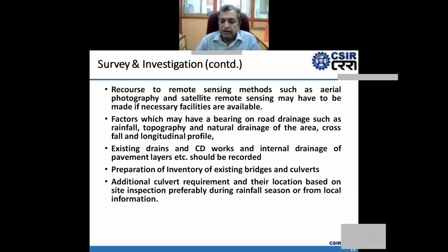Preparation of inventory of existing bridges, culverts, or natural causeways. Additional culvert requirement and their location based on site inspection, preferably during rainfall season or from local information.